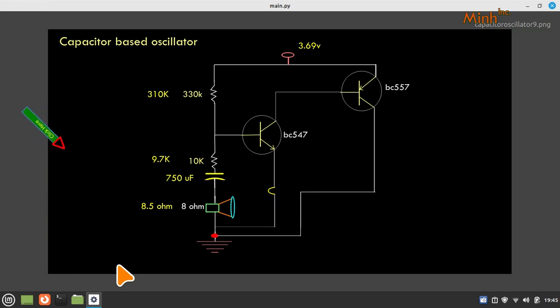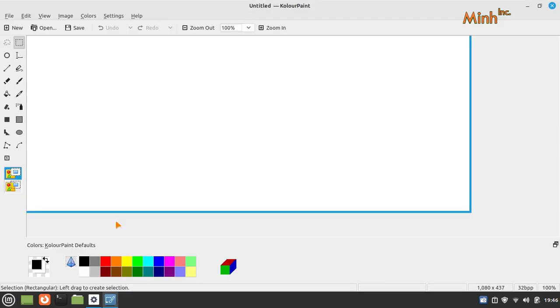Now we will measure the voltage across the capacitor, the voltage and current across the speaker, and then the emitter current, collector current, base current and base voltage. Then we can interpolate the others that can also be calculated. So what we'll do now?